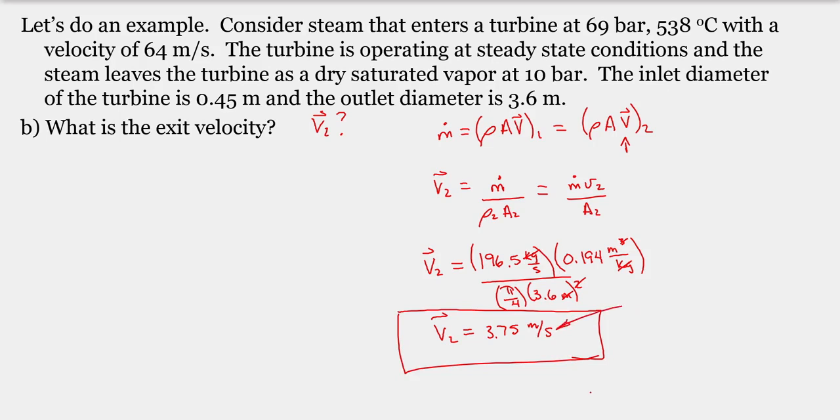We look at the number and say, does that look reasonable? And again, I don't expect you to have a good feel for speeds of fluids at this point in time, but we'll develop those tools as we go through this class. The other thing that's really useful as you go through these types of exercises is to look at things like, okay, the mass flow rate we know is proportional to density. It's also proportional to diameter squared and to speed. So if we wanted to double the diameter, we're going to have a quadratic effect on the mass flow rate. So it's good for us to understand these ratios, to understand what happens as we change physical dimensions or if we change thermodynamic properties.